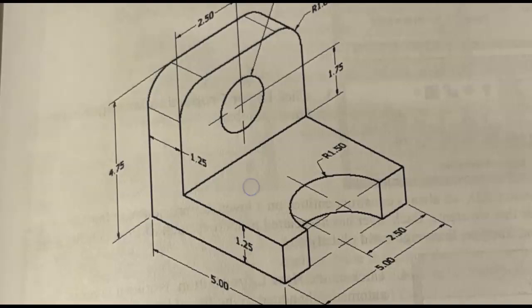All right, I'm going to left click to place this, and then I'm moving my cursor up and to the left because I want to get that over there, moving at 30 degrees. The line length here is going to be 5 inches, so I'm going to hit 5. Then the tab button, and this is going to be at 150 degrees. Then hit enter. So I've got that in place.